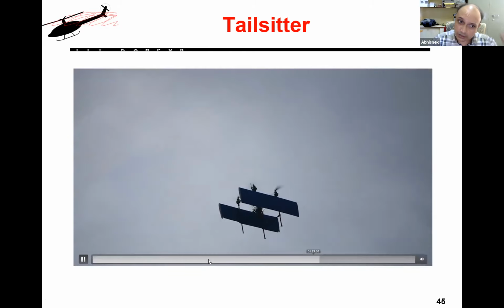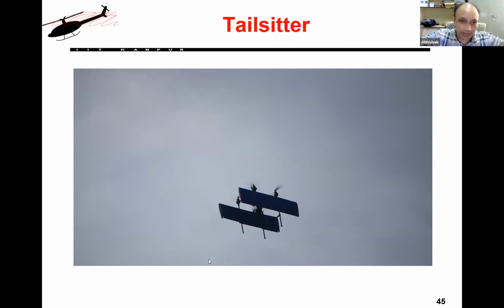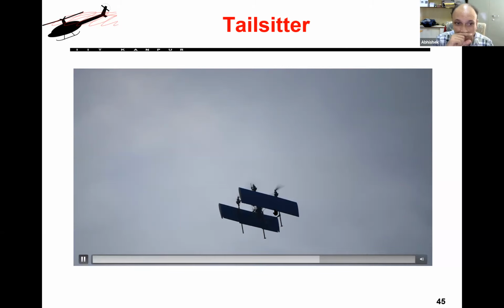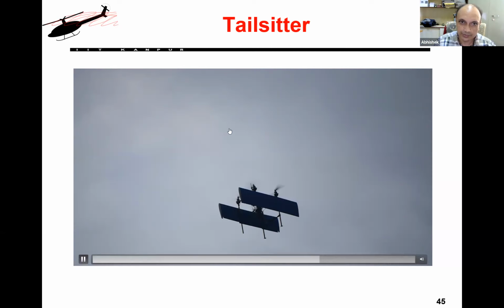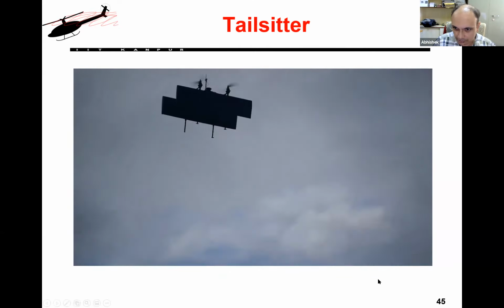Not exactly. The yaw in normal quad rotor drones is done through torque imbalance. Here we actually give a thrust imbalance. So 2 rotors have higher thrust, other 2 rotors have lower thrust. So it's yawing through that. You create a moment between the 2 thrust vectors from 2 sets of propellers. So it's not quite like that in a normal quad rotor. When it is hovering and you try to yaw using the torque reaction, you will see it will be very sluggish. So we have put these ailerons, which work like a yawing vane, which allows you to do pretty fast yaw motions. Now this is the video where you see it doing the manual flight.